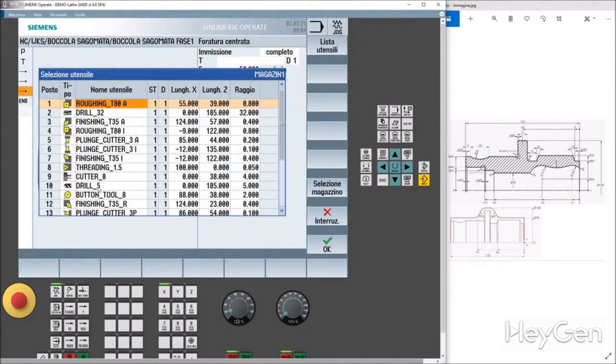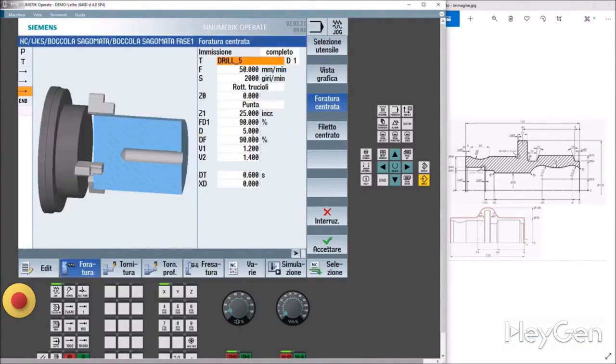If we don't have it, we'll put it in. All right, drill 5, look. We have the bit. We have the diameter 5. We're just going to modify the diameter. Of course, this will correspond to going to the machine's turret. Check that there is a 32mm bit in position 10. It probably won't be there. You need to put it in and zero it out. Unfortunately, with a PC, I can't show you the whole operation, but we'll have your workshop heads do some of it too.